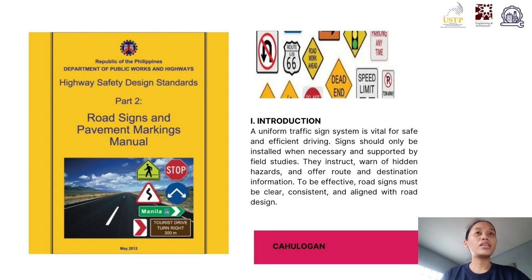Signs should only be placed after careful field studies. Engineers evaluate traffic volume, roadway geometry, crash history, and sight distance to determine whether a sign is necessary and where it should go to be most effective.